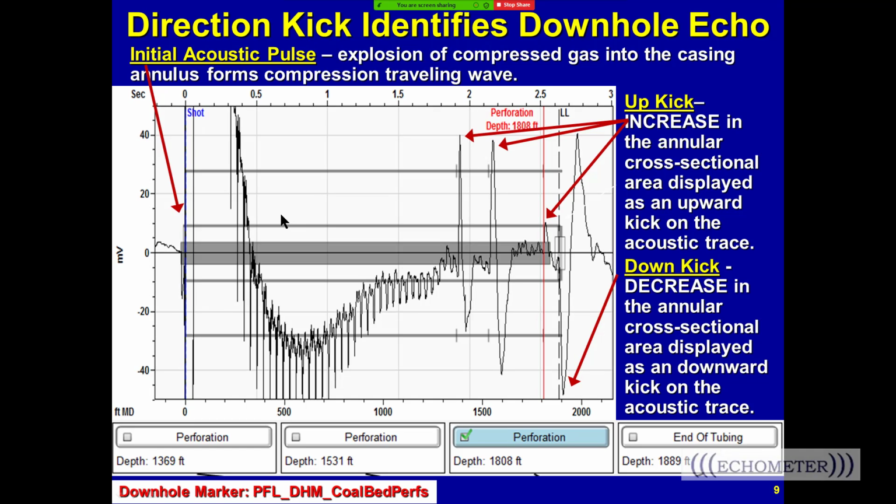If you overlay the wellbore, now we've got a mark on the wellbore that shows a perforation, another perf, and then you can't really see the perf marker right there. But now you can see that the beginning of this upkick, right at the knee, right where it first bends, matches that perf, that mark. The upkick right there matches that perforation. And this is the perforation that we use, the deepest perforation closest to the liquid level, to determine the distance to the liquid level.